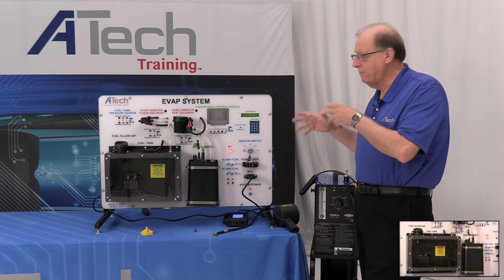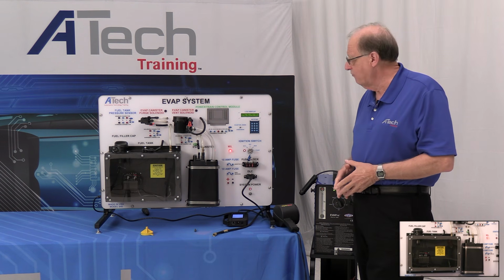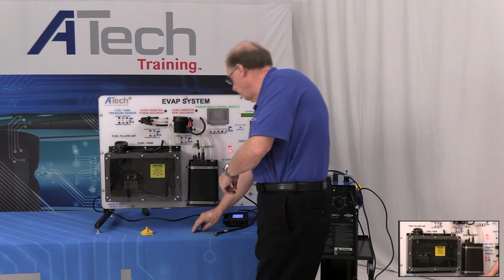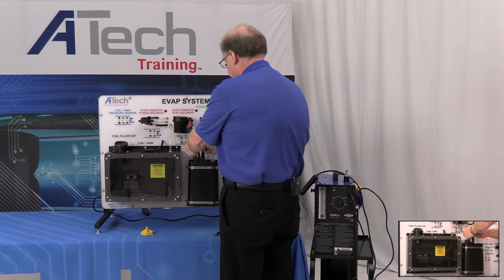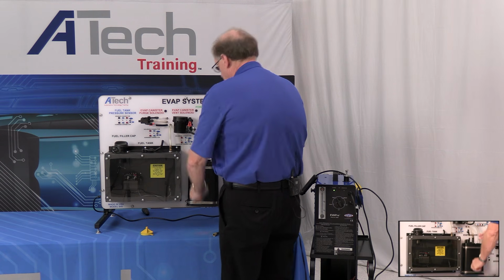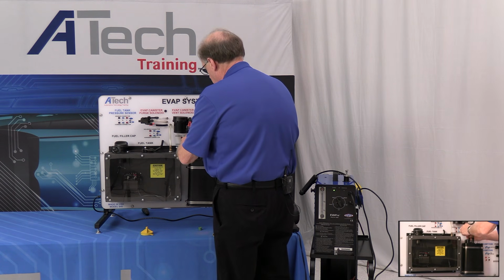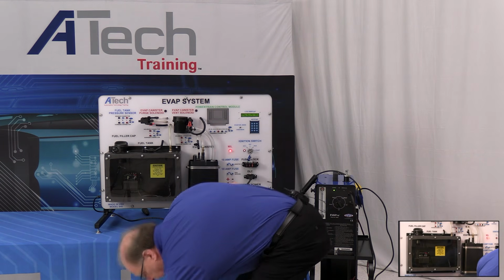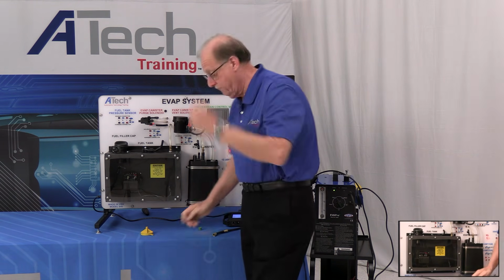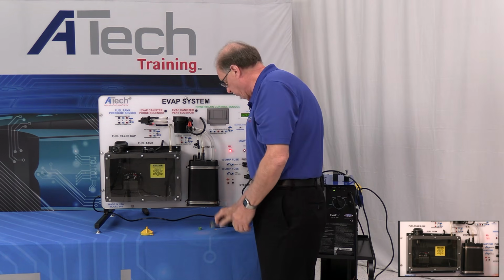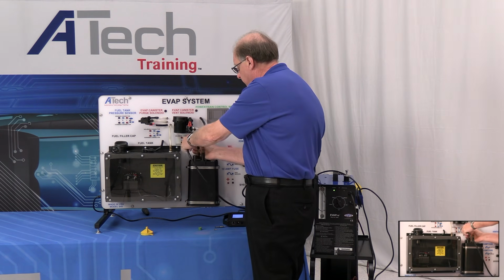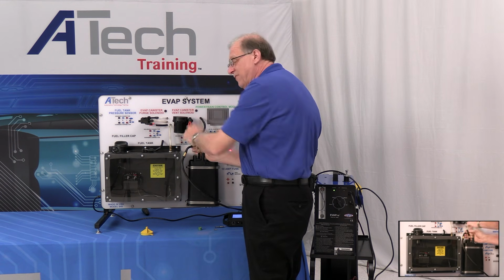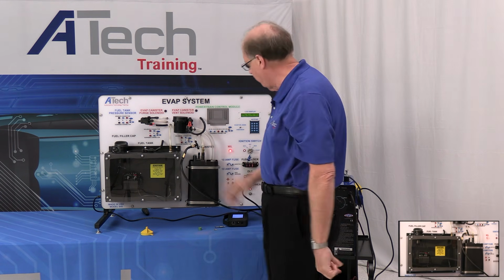Okay, we have to set up the system to be able to test it. So the first thing we want to make sure is if you have the test port, you want to go over, take off the green cap. Remember, this is left-hand thread, so we're going to undo that, and then I'm just going to flip it down in the process and drop it on the floor. So here's the deal. The next thing we're going to do is attach our smoke machine up to the unit. Remember, it's left-hand threads for the Schrader valve, but right-hand threads for everything else.